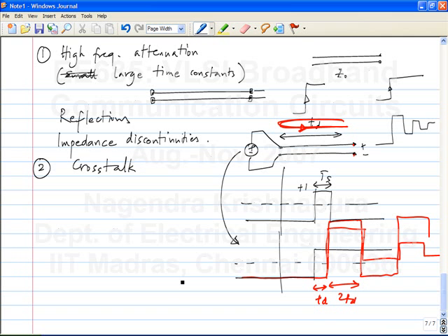That is, we are happily saying that we'll transmit ones and zeros, and the symbol period is TS. Now TS is known. Even if it is known, it's not exactly known. There is always some parts per million type of error. But that can give you significant errors, okay? Because you don't know exactly where the bit starts, where the bit ends, or how long the bit is in many cases, okay? So, the third issue with transmitting digital data is timing.